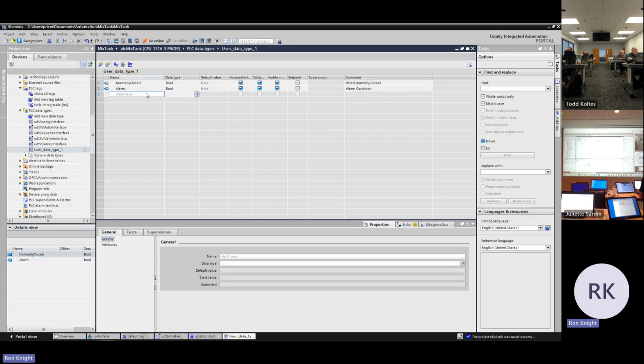And maybe we want to be able to set the debounce time from the operator interface. You know, if the level's right at the level switch, alarm may chatter, upsets the operator. You never want an upset operator. So maybe we want to debounce that signal a little bit.